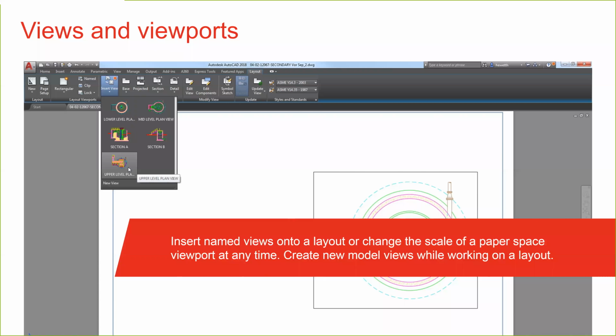You now have a new named views panel, which is added to the view ribbon tab. And you now have tools that help you to easily create and edit named views. So you have the view drop-down list in the panel, and you can easily restore named views by selecting from that drop-down list. So it is basically a simplified version of the new view / shot properties dialog box. And this time you have just the basic controls for creating a new view.